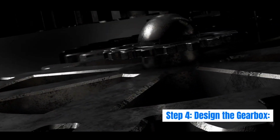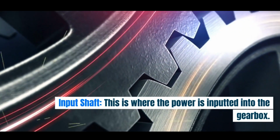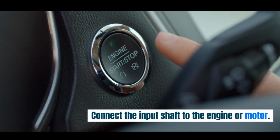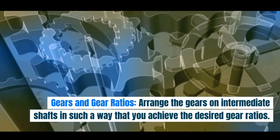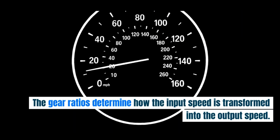Step 4. Design the gearbox. Input shaft. This is where the power is inputted into the gearbox. Connect the input shaft to the engine or motor. Gears and gear ratios. Arrange the gears on intermediate shafts in such a way that you achieve the desired gear ratios. The gear ratios determine how the input speed is transformed into the output speed.